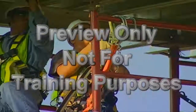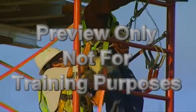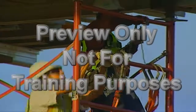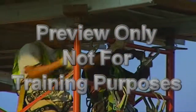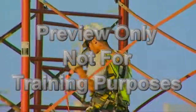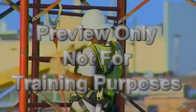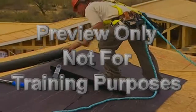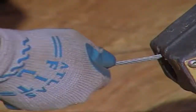Maximum intended load of a scaffold is the total of all persons, equipment, tools, materials, transmitted loads, and other loads reasonably anticipated to be applied to the scaffold or scaffold component at any one time. A personal fall arrest system is a system used to arrest an employee's fall. It consists of an anchorage, connectors, a body harness, lanyard, deceleration device, lifeline, or combinations of these.